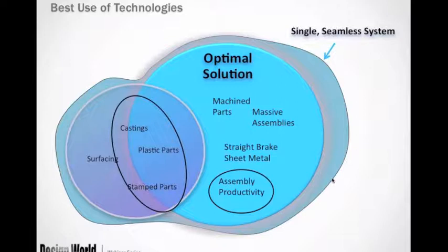So again, I don't think you ought to have to choose, nor is it right to choose and say, history-based, history-free. You should be able to do a design where the design basis is history-free, and some of the manufacturing aspects are history-based, and that should all happen within a single piece of software in a single file.